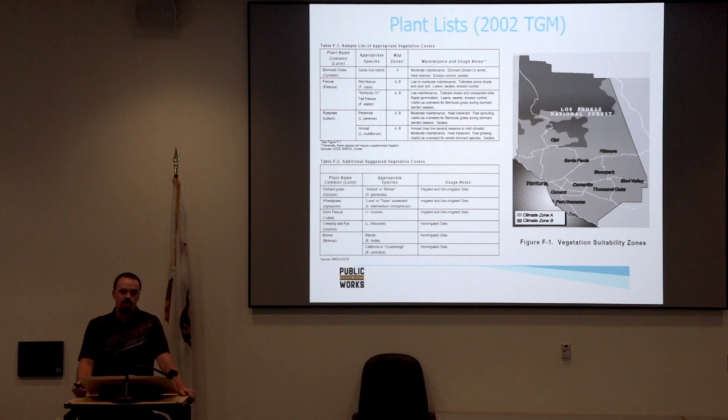So that could be used for your vegetation, for your vegetated swales, bioretention, but it doesn't list a lot of stuff like, well, how well does it do if it's inundated for 48 hours when you're drawing down a detention or a bioretention area? How much water does it need if you're trying to go sustainable? It doesn't have that information on here.